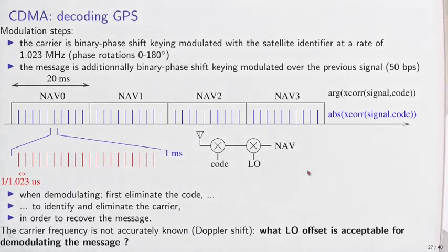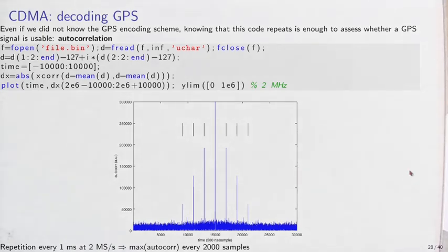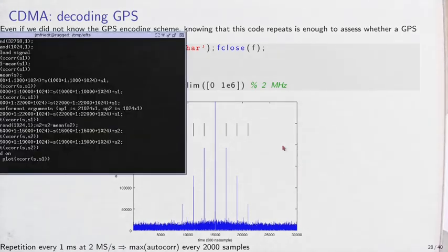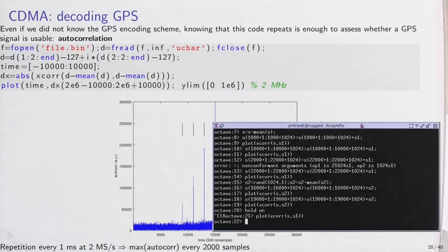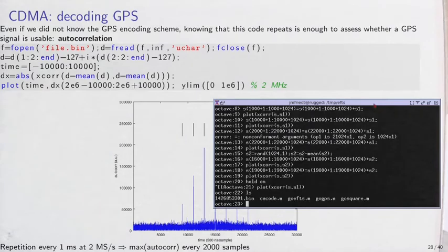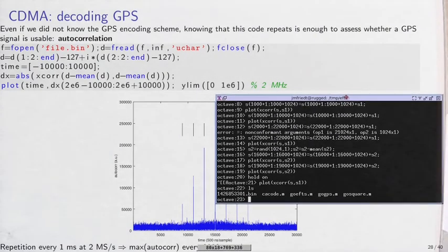Now, prior to actually testing this hypothesis, we can read data and try to check whether data are indeed valid. So you will have a link to some of the data sets. These data sets that we are sharing have been collected using these DVB-T receivers, and they are binary files, which are the basic storage format of this DVB-T output. These are 8-bit data, unsigned 8-bit integers that need to be read, and we need to know that they have been sampled at 2 megasample per second. This you cannot know, so 2 megasample per second is the data rate.